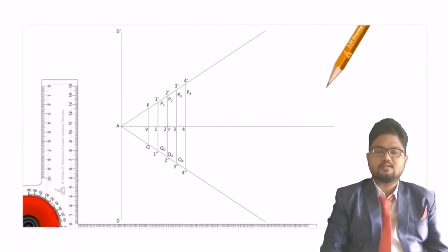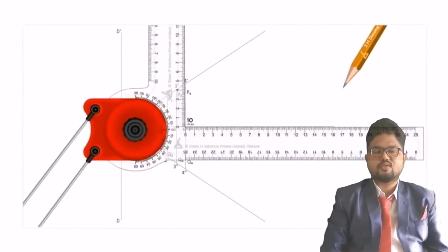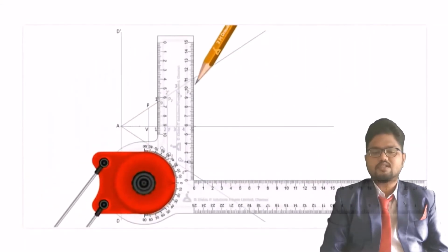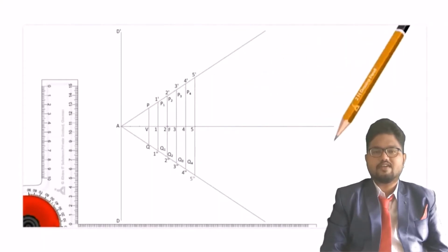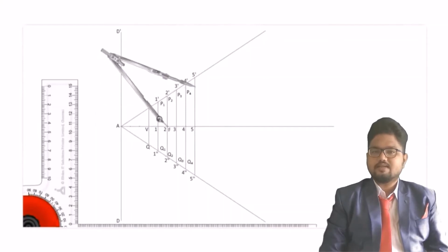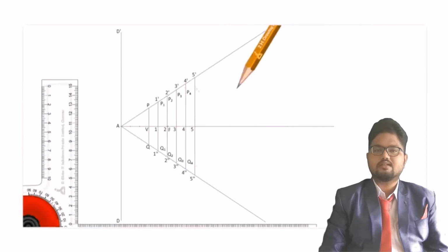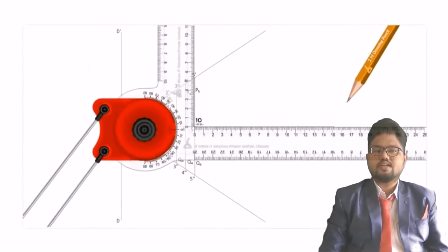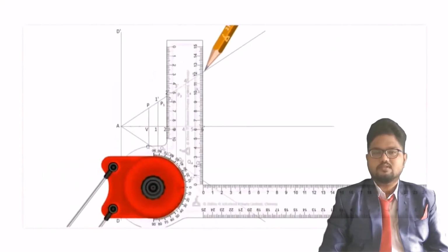In this way, plot the curves where you are cutting the lines, and name them with P and Q notations. Now, in that way, take the fifth point and draw a line towards AP and AQ. Now, with 5 dash radius, F as center, do the same procedure of cutting the arcs on the lines. In this way, you cut each and every line one by one. So, at one particular point of time, you get the closure of the curve.